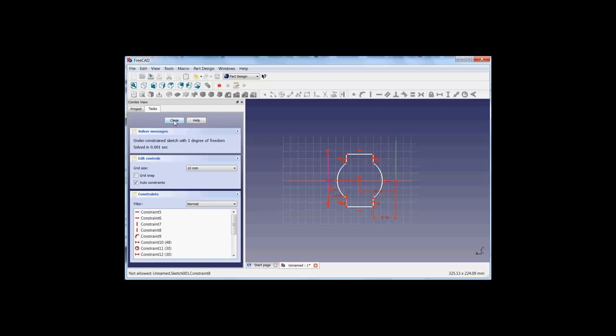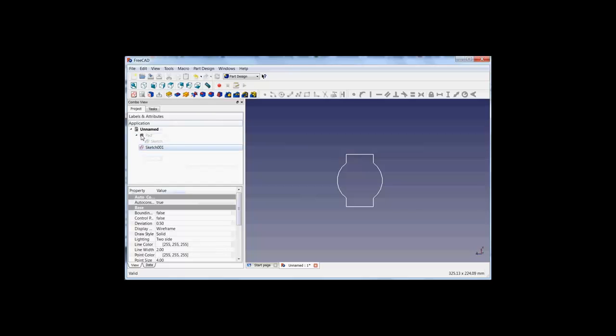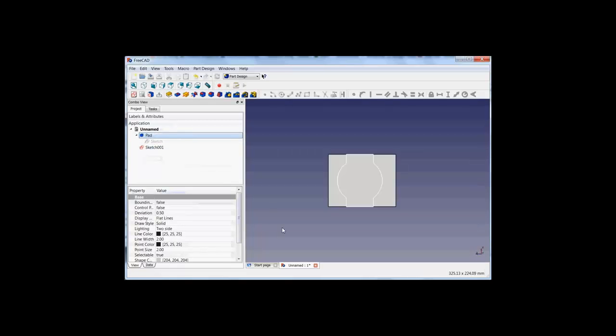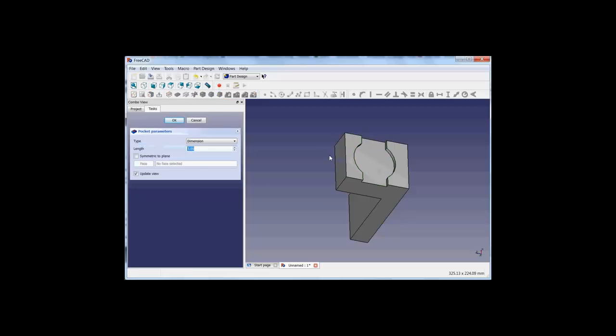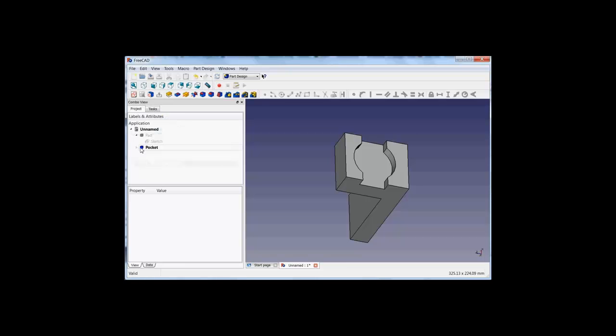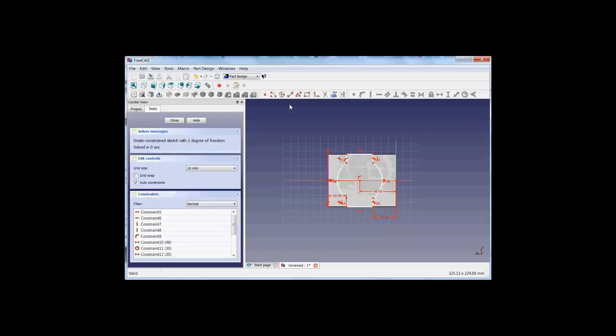Good. Close. So what we have now is this. This is a complete sketch. It's not completely bug-free, as you see, but with some patience, you get it all done. Then okay. The nice thing, if we can again look at the sketch, is that FreeCAD did for us some work. Namely, this circle are now two arcs, two half circles, and of course they should have the same size. And you see here that it automatically added